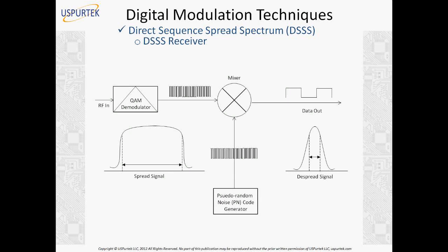Any bit stream or data stream can be represented as an equivalent of components of frequencies, and that is true. You can do a Fourier transform to see that. So higher bit rate means higher bandwidth, and lower bit rate means lower bandwidth. As a thumb rule, we can just see that, but mathematically you can prove it, and you can prove it in the lab also.